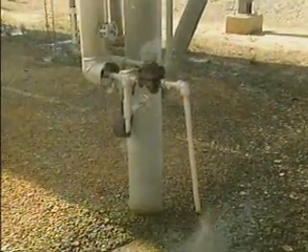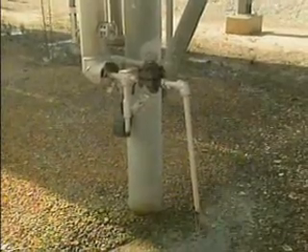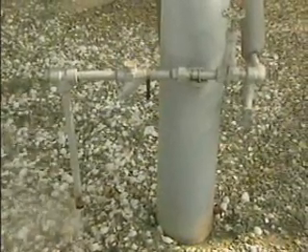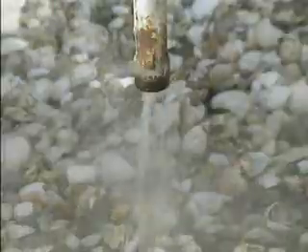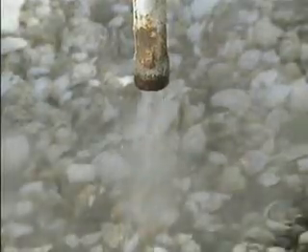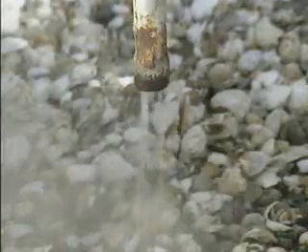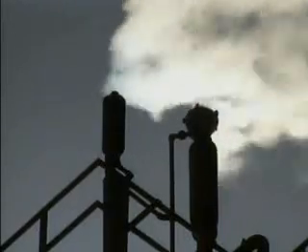Of course, before you can determine if a trap is discharging live steam, you must be able to recognize the difference between flash steam and live steam. Flash steam is a normal condition in which vapor is formed when hot condensate is discharged from a trap. Normally, the discharge from a trap consists of a center core of hot condensate with a slowly moving white cloud of flash steam circling the outside. Live steam is produced in the steam system's boiler. It's usually discharged with more force than flash steam is, and it has no center core of hot condensate.